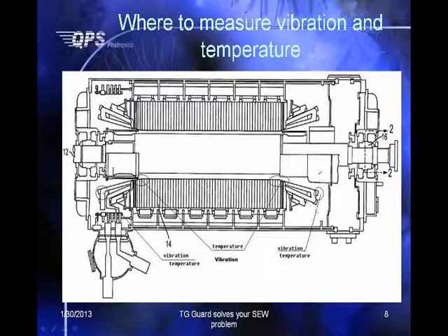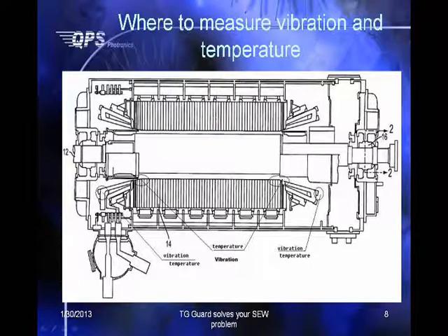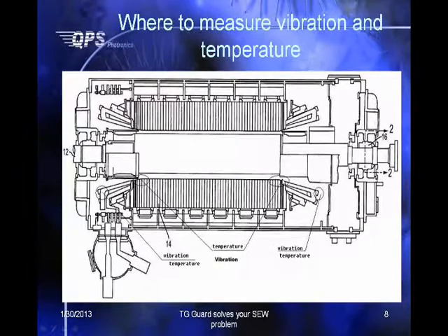So besides placing vibration/temperature sensors on these end windings, you could also verify if the cooling mechanism is adequate by placing some sensors at the lip of the stator. This is the area where the gas flow will probably have a pressure drop and it will be flowing at the lowest rate, and that becomes the worst case.